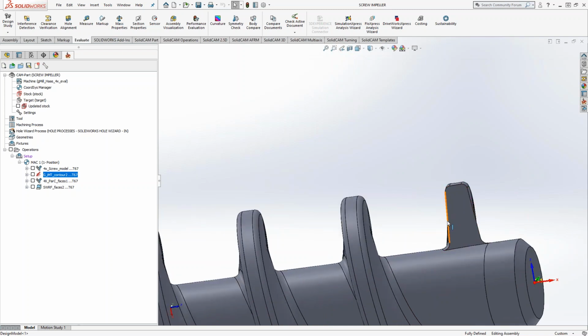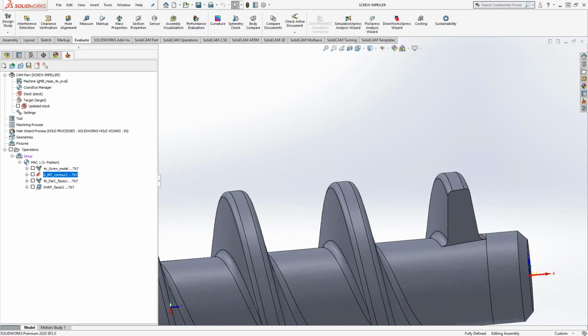So with the walls, because the wall actually has a little bit of an angle to it, that is not fourth axis anymore. Well, actually, it is still fourth axis on this machine, but it's not allowing us to just point towards the center. So we need some sort of simultaneous toolpath. And that's what we talked about yesterday.